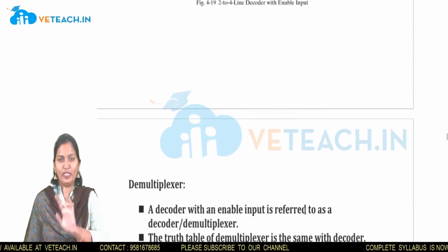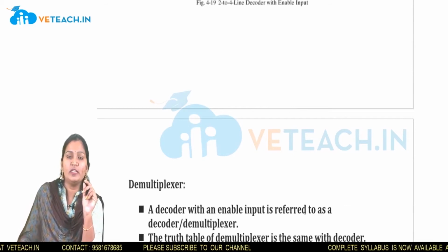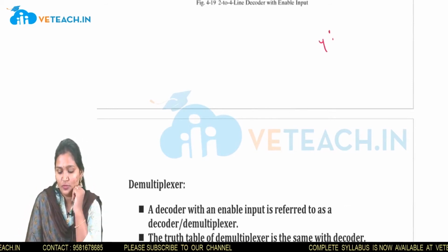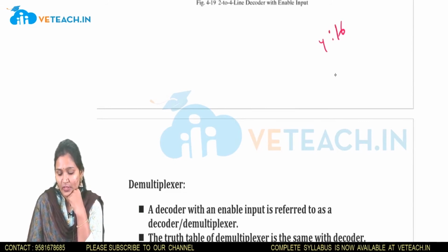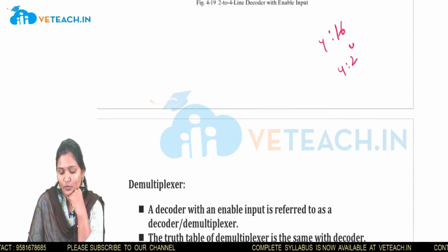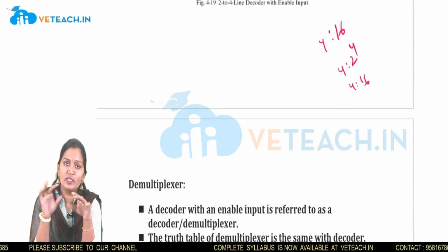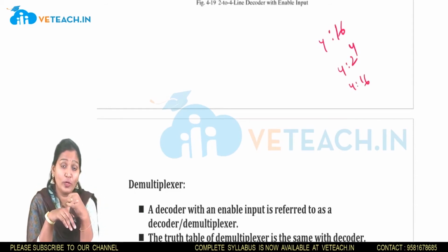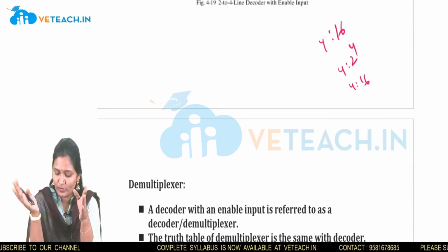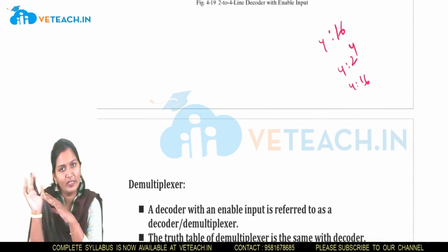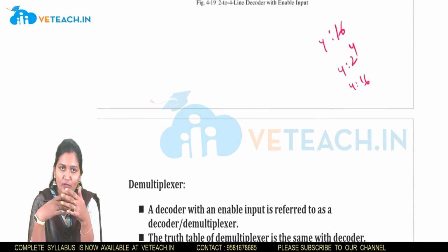We have learned about the 3 to 8 and 2 to 4 decoders. So they may ask you a question like design a 4:16 decoder, means if we have 4 inputs we get 2 power 4 outputs, means 4:16. So that is also the same way. First write the truth table for 4 inputs, means A, B, C, D, and the outputs are 16 outputs, means D0, D1 till D15, okay. Same process but it takes a long method, okay.